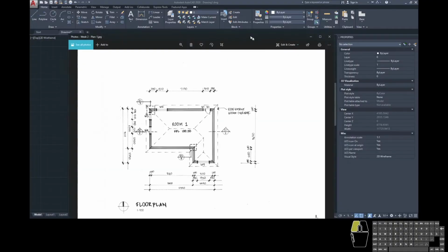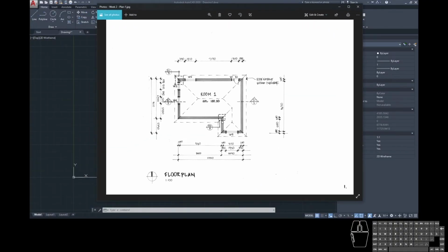Now if we have a quick review of our plan, we've just done our 8400 line here. We're going to now come down, which is going to be a 2390. We're going to come across with a 3590. We're going to come up, which is not this 8630 because that's minus the width of the walls on the end. This wall is actually the 9110, and we're going to come along, which is our full length 11990, and then we'll come down here, which is our 6720.